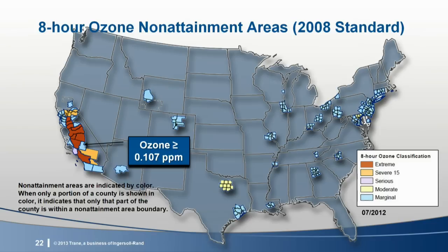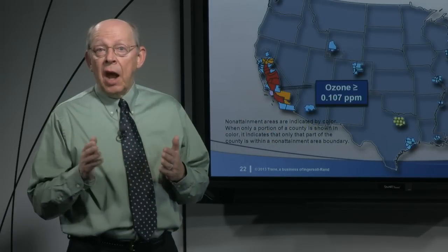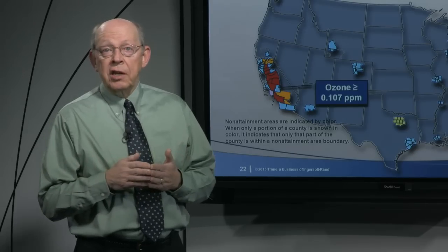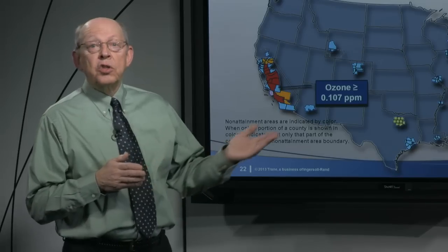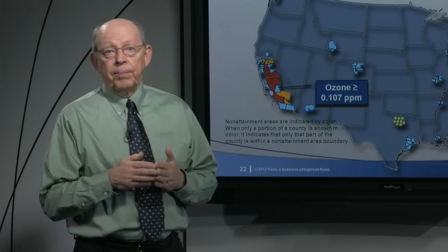Buildings located in ozone non-attainment areas other than Southern California don't need air cleaners to meet Standard 62, but designers might want to consider using them anyway. After all, breathing ozone is harmful, and besides that, if you're designing a high-performance building, Standard 189.1 requires 40% efficient ozone air cleaners in all ozone non-attainment areas, which includes most of California and many major metropolitan areas throughout the U.S. As Dennis mentioned, we're only going to focus on the ventilation rate procedure for today's program.